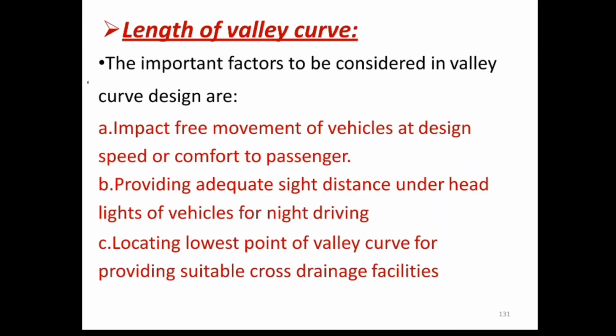The important factors to be considered in the valley design are, first, the impact-free movement of the vehicles at the design speed, or comfort to the passenger. That means no sort of discomfort or impact has to be experienced by the passenger. Second, to provide adequate sight distance under the headlight of the vehicles during the night driving. And third is locating the lowest point of the valley curve for providing suitable cross drainage facilities.